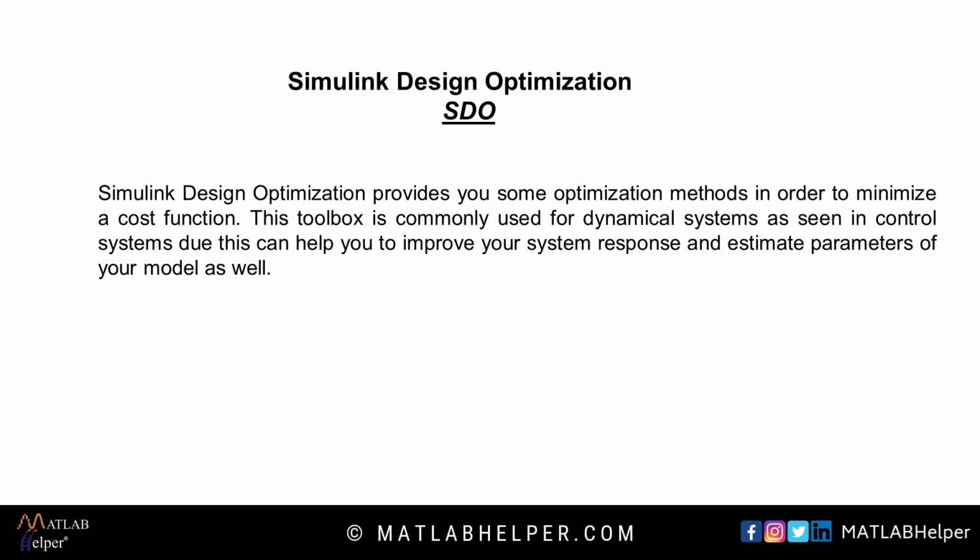So, Simulink Design Optimization provides you some optimization methods in order to minimize a cost function. This toolbox is commonly used for dynamical systems as seen in control systems. This can help you to improve your system response and estimate parameters of your model.